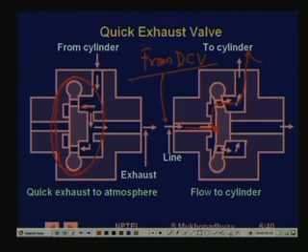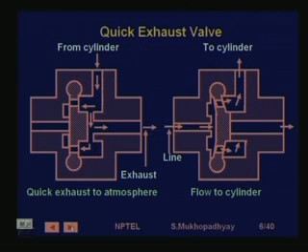This will press it, and therefore this will close and the air will actually flow out into the atmosphere locally at the cylinder. So, it is quickly exhausted, right. So, that was the idea.